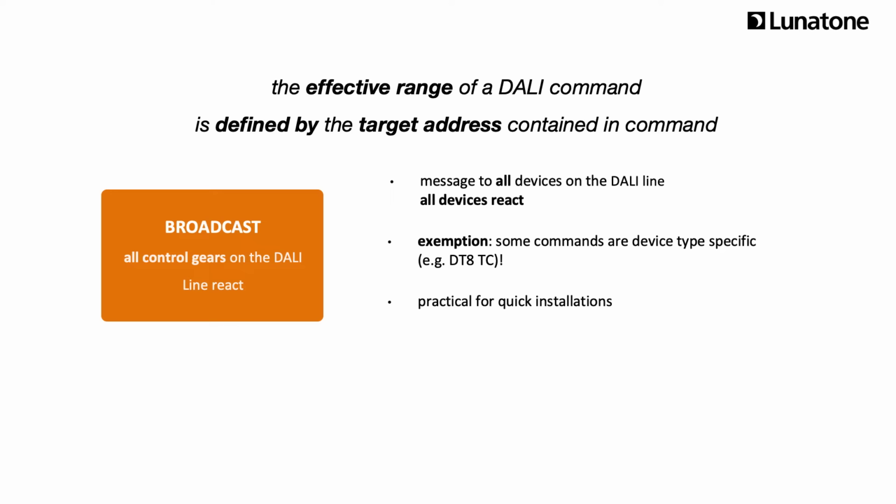For example, in an open plan office space with one control unit, one motion sensor and multiple luminaires that behave the same way, the DALI commands can be broadcasted. Also, the factory settings of the control unit could be sufficient for such an installation. To conclude, for basic installations, neither addressing nor an adjustment of settings with a software tool are necessary. Lunatone offers several pre-programmed control units for such installations.